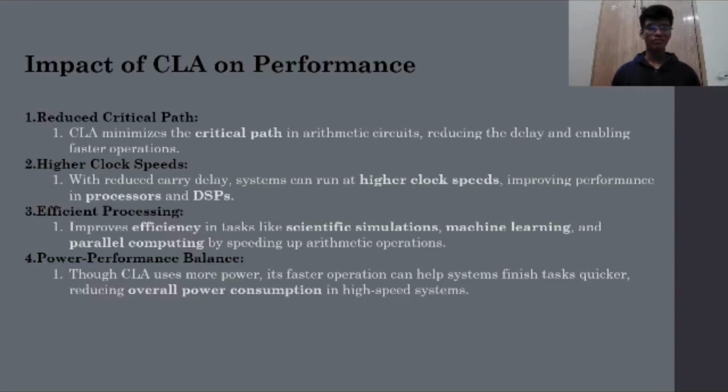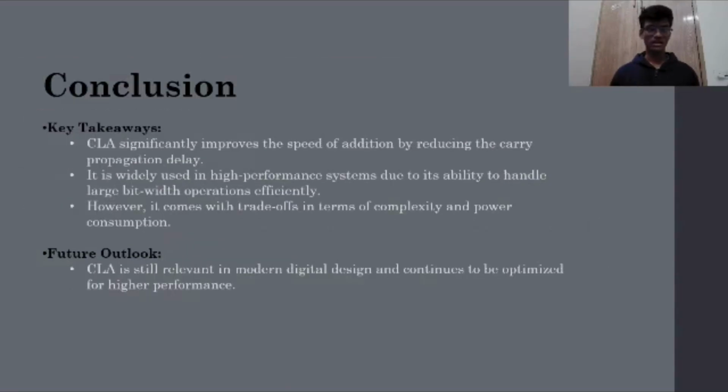operations. Power performance balance. Though CLA uses more power, its faster operation can help the system to finish tasks quicker, reducing the overall power consumption in high speed systems. Conclusion. Takeaways. CLA improves the speed of addition by reducing the carry propagation delay.